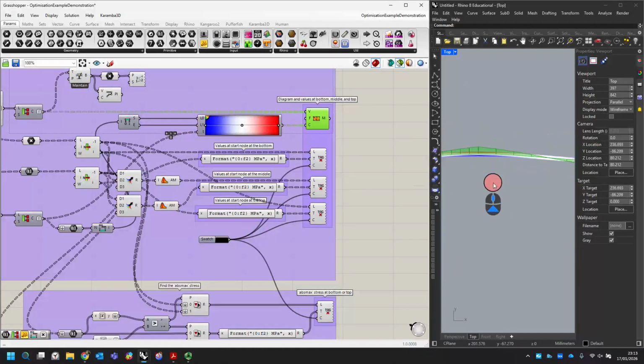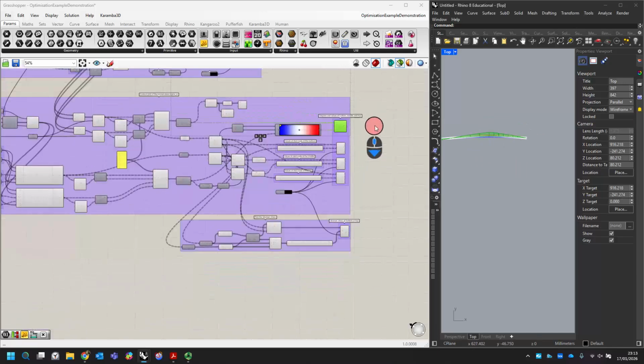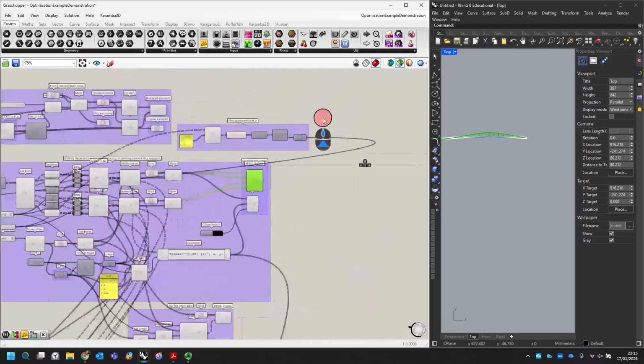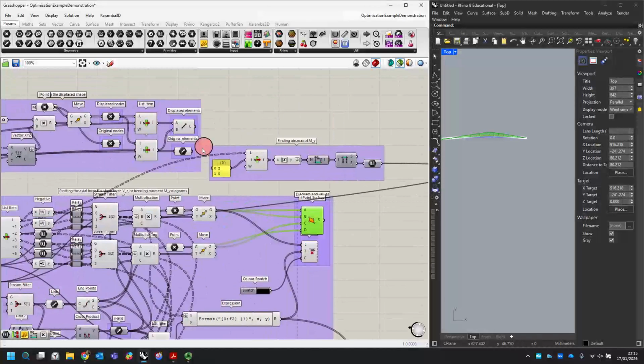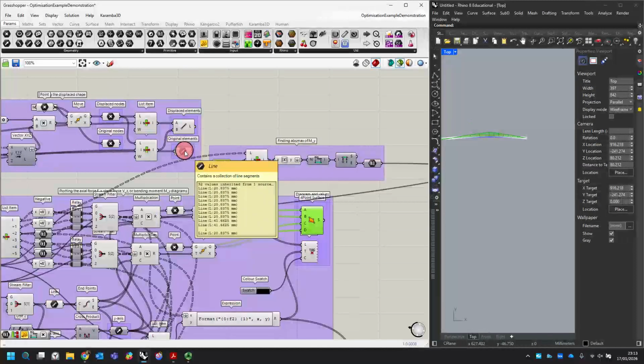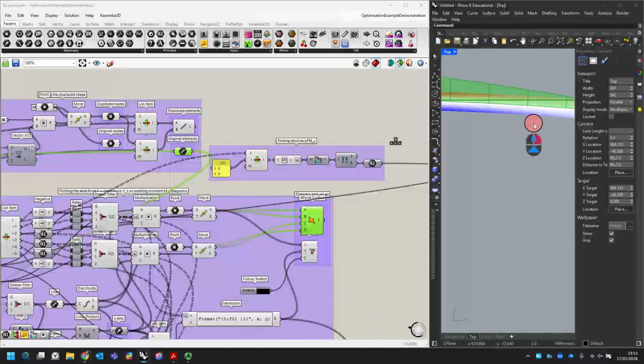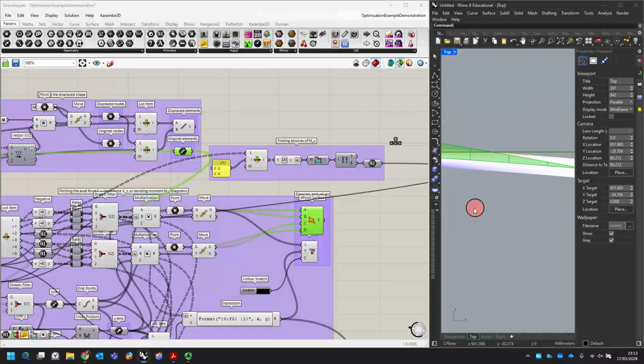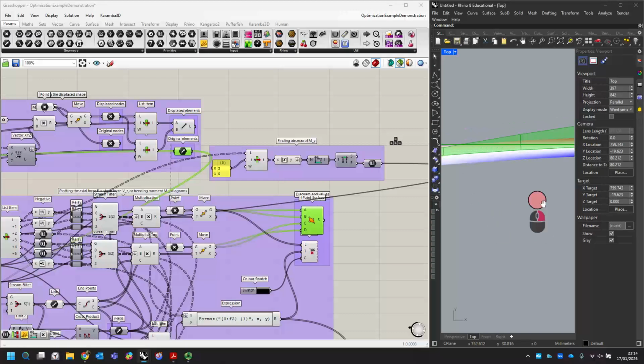So we can now see that the displaced shape is fairly much following the bending moment diagram. And if I add in the final thing, what I want to do is just show the original elements so you can see how the regions of tension and compression are obviously reflected in the displaced shape, and also the bending moment diagrams.